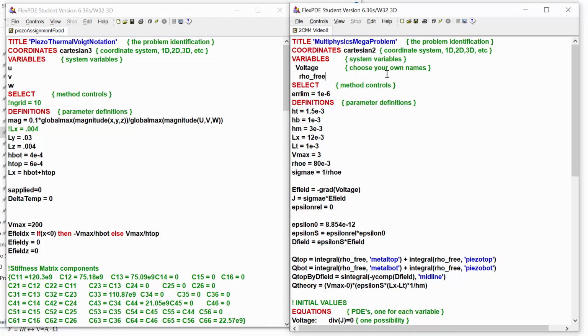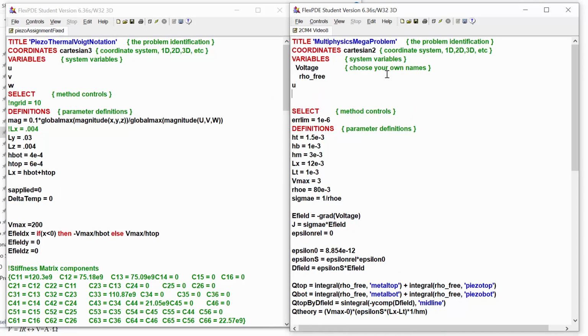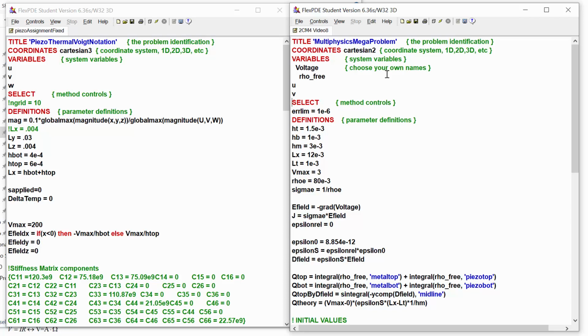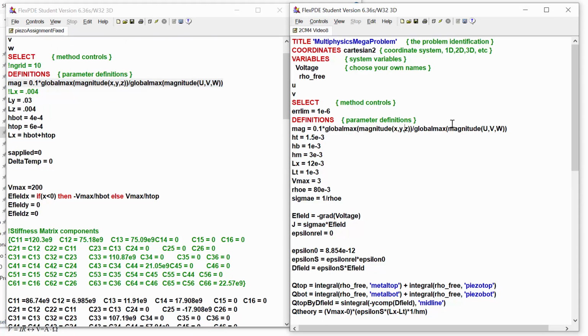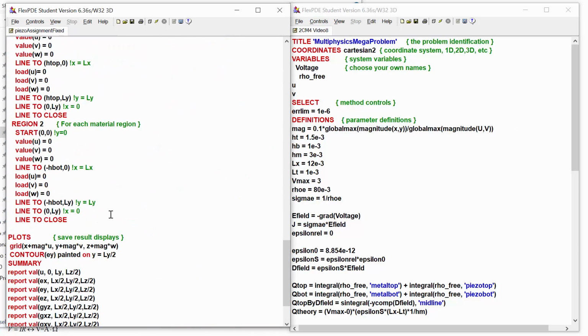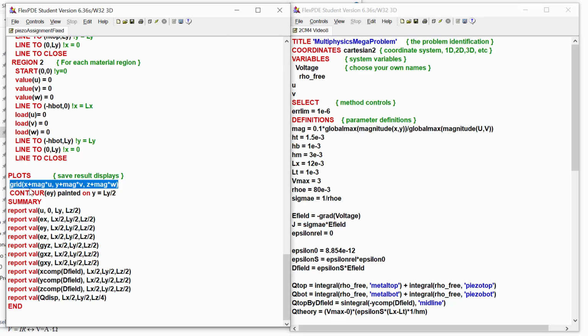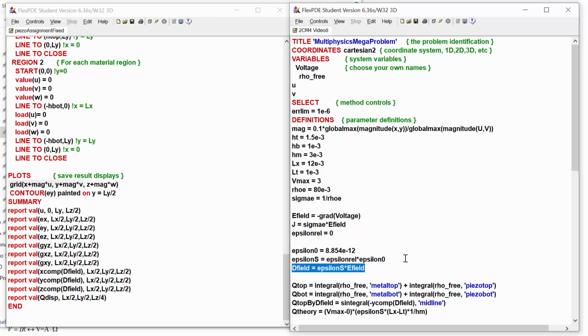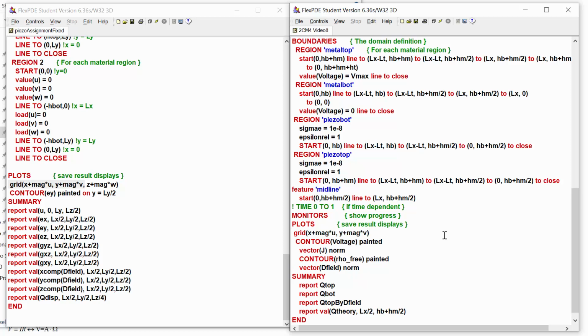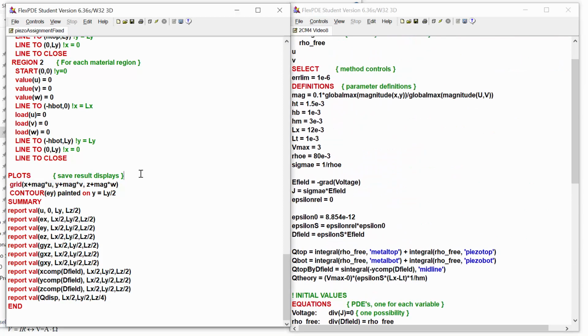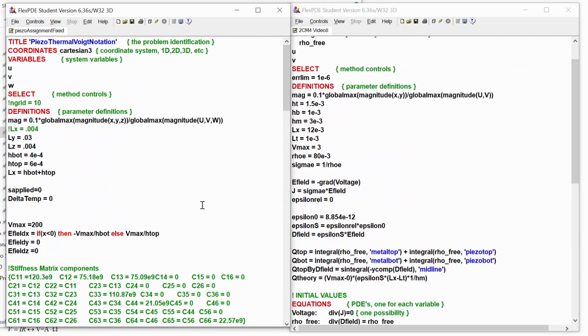What we'll do is we'll keep it in 2 dimensions. So we'll just have a variable for u and v for the displacement in x and in y. Then we'll add in this global max magnification thing, again converting it to 2 dimensions so that we'll be able to have a good displacement plot later. Maybe we'll put in that displacement plot now. So this is the grid plot stuff that we're going to need in the plot section, just so we don't forget to do that. Yeah, okay, that's good.